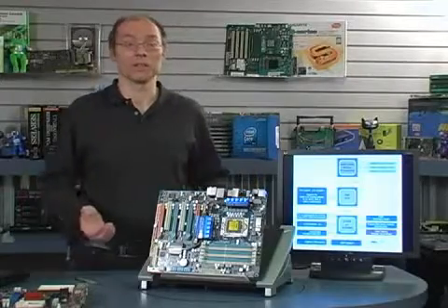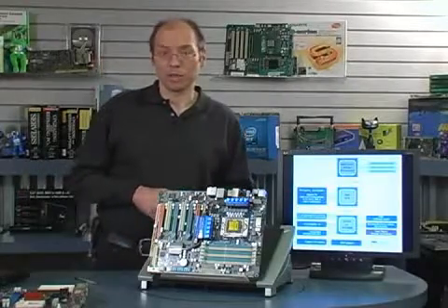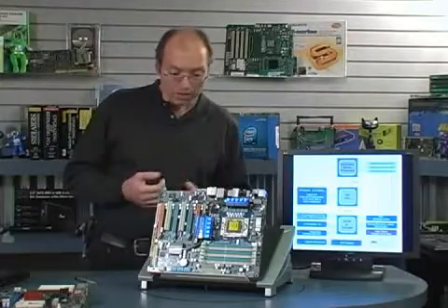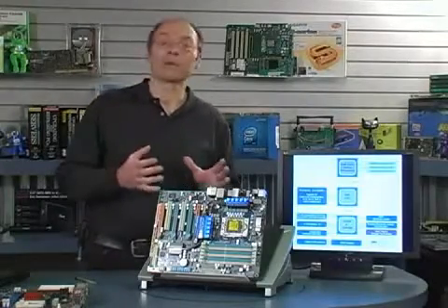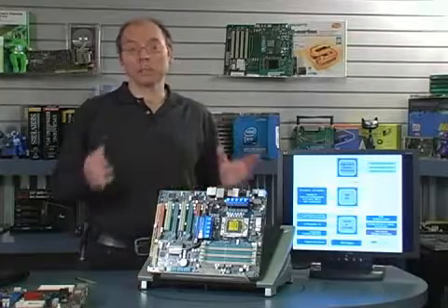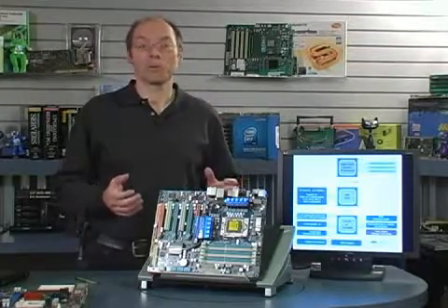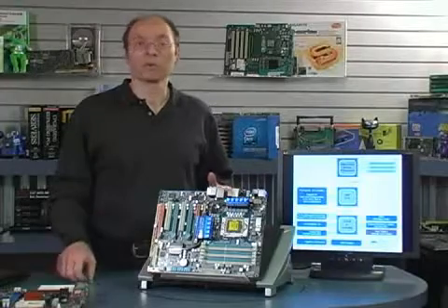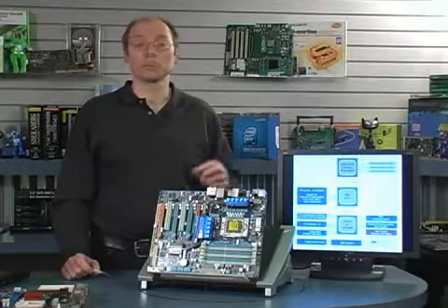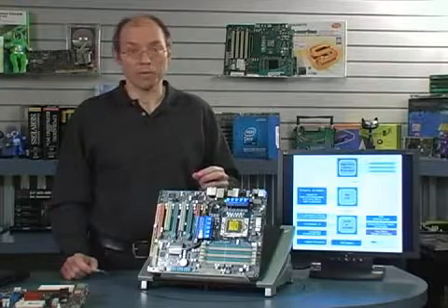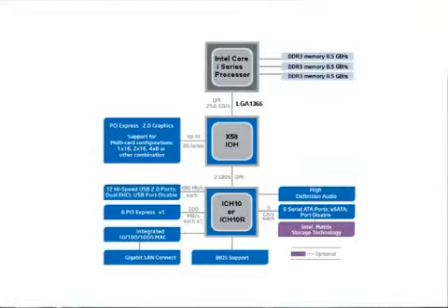Now, normally when you're putting together a system, buying or building, you're going to decide, oh, I want this certain type of processor. Then that gives you a range of chipsets to consider. See, the main circuitry on the motherboard is what we call the chipset. Now, modern motherboard chipsets normally consist of 2 chips, what we call the north bridge and south bridge. I have a diagram here showing a typical motherboard block diagram, and the north bridge and the south bridge are these components here. The processor would be in the socket represented by this top portion of the diagram.